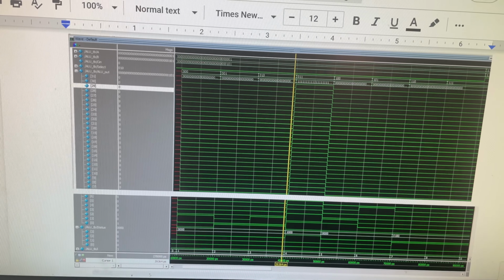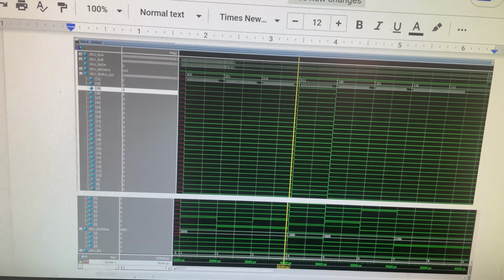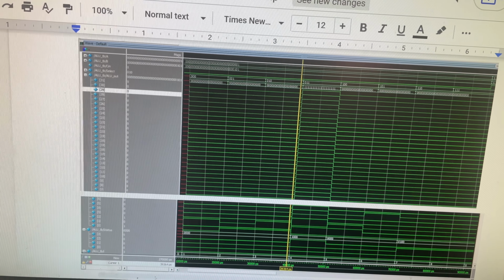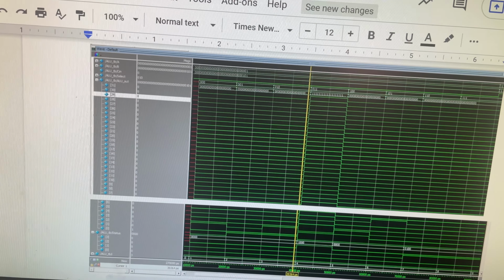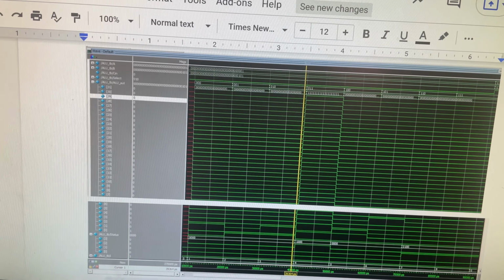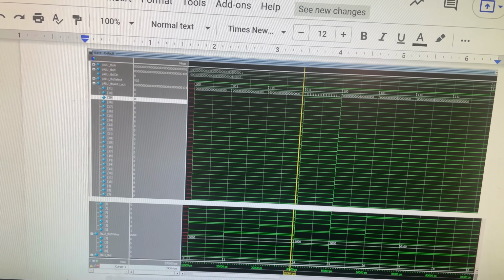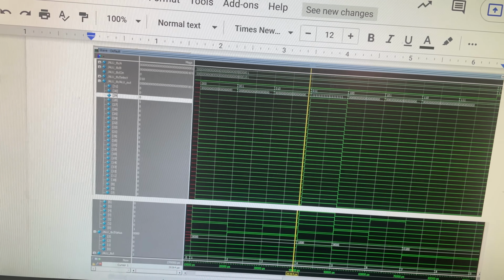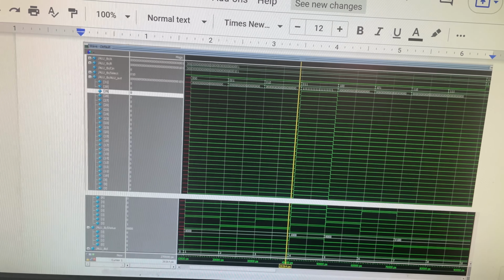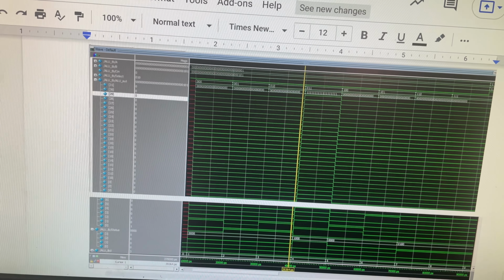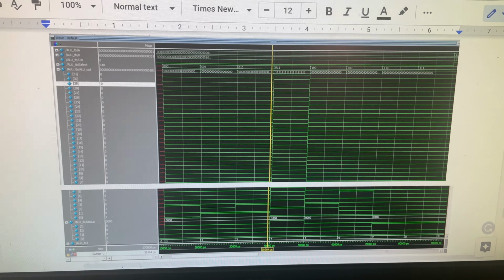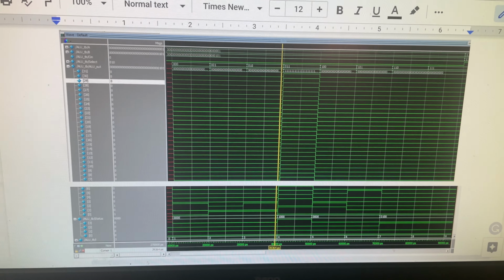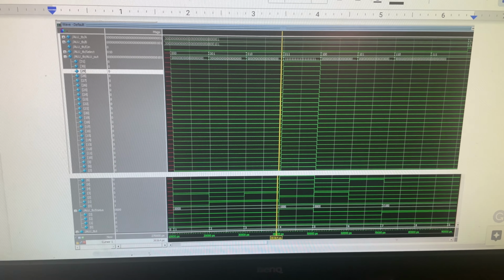The ALU has the status values, which is the carry out, which is C out, of the adder / subtractor. It has the overflow V, which becomes 1 if the sign bit of the inputs of the adder / subtractor are the same number. And it has Z for 0, which becomes 1 if the output number of the ALU is 0. And we have N for negative, which becomes 1 if the sign bit of the output is negative.